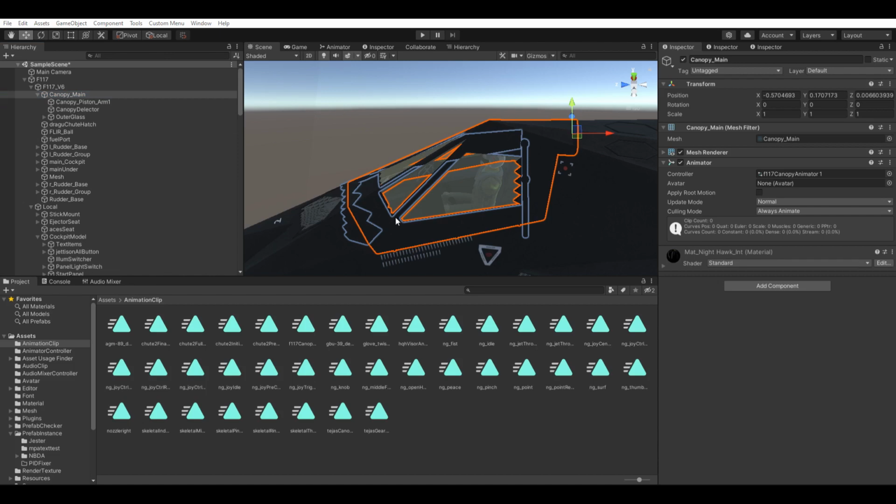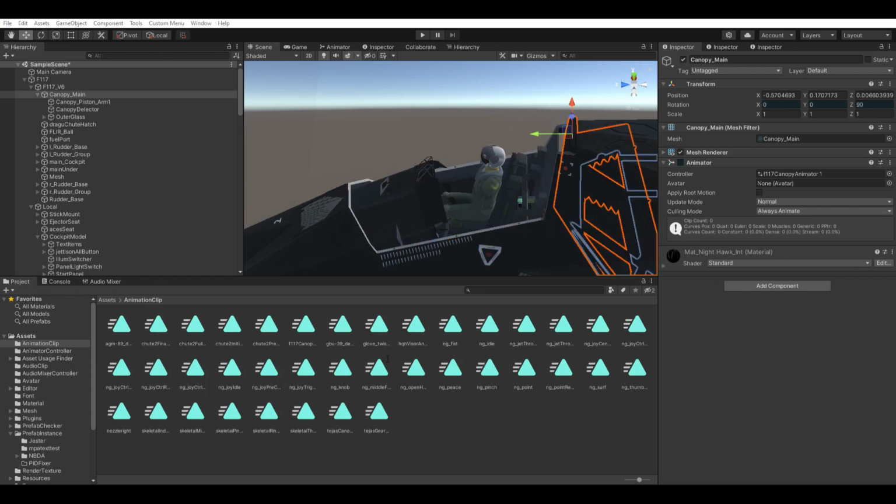What we can do is click on the transform because we know we're in the right place there. And we can click on rotate, and that will add the option to rotate for the animation. What we know is it's along the blue axis there, so Z. Obviously no animation exists right now. So if we come onto here and type in 90, you can see it animates.